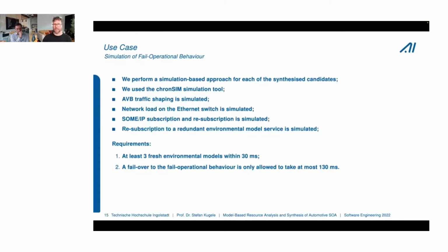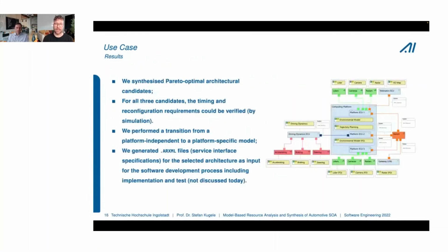And the requirements were that within 30 milliseconds, we need 3 times a fresh environmental model. And if this is not given, then the system performs a reconfiguration. And for this complete reconfiguration, we have a time of 130 milliseconds. Yeah, and the results are that all 3 candidate solutions which have been synthesized are actually valid, which means they are all supporting the bandwidth, the end-to-end latency, and the real-time requirements.